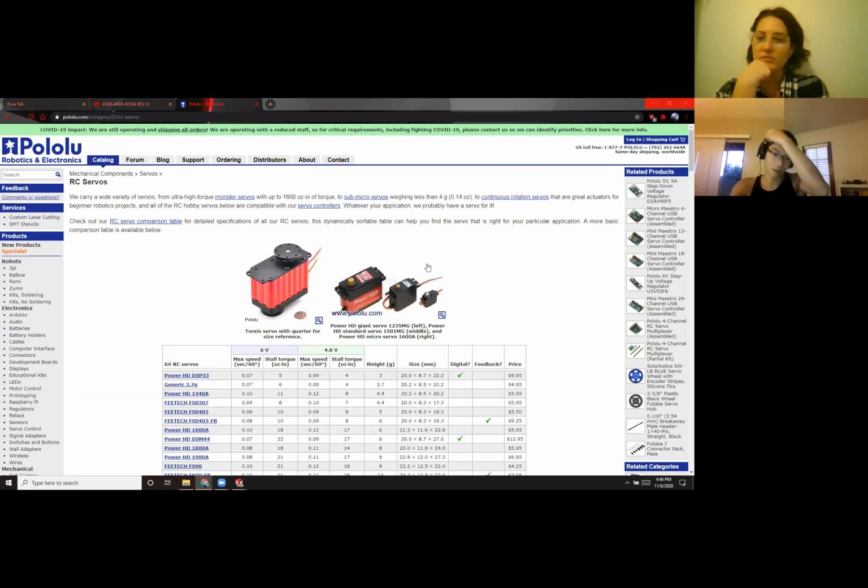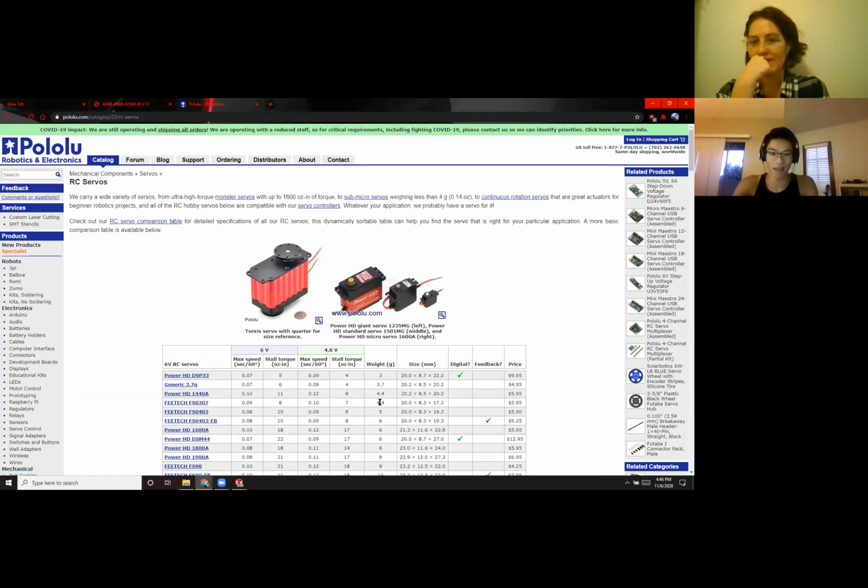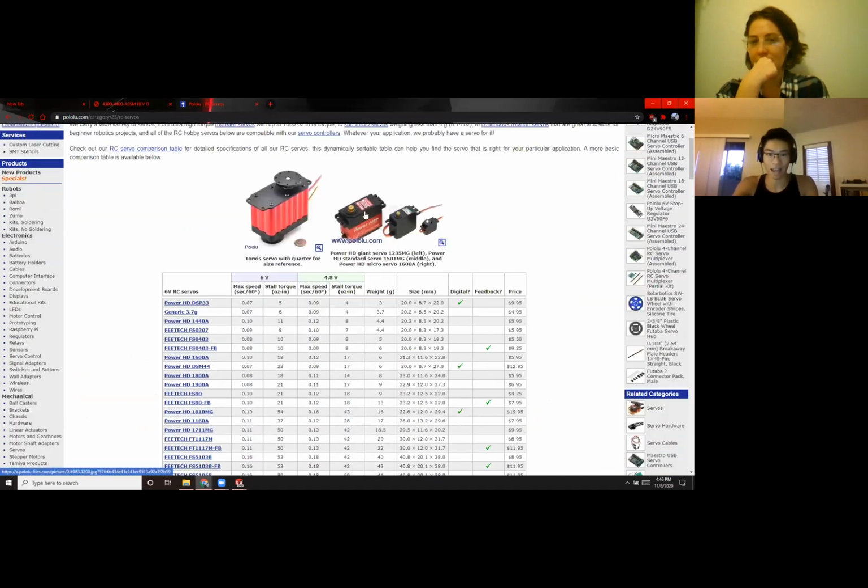Essentially, let's say maybe I was using this servo over here, right? And realized that wasn't working, and then I look at the spec sheets, I do the math, and I say, okay, I need that guy instead, the big one, right? And obviously, you can see this servo is bigger, it has a different footprint, the screw holes are spaced out differently. And all right, so I'm not only going to need to make a change, I'm not going to be able to just pull out the old servo and put the new one in. I'm going to have to actually change some parts of my actual arm assembly that the servo is stuck onto.